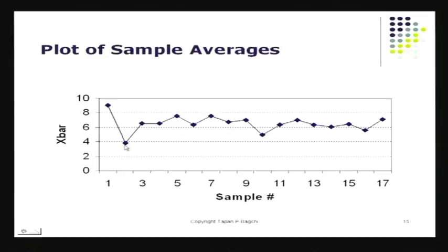So again, let's take a look at it. We saw the plot of the raw data. The same data was converted into X bar, and I'm going to be showing you how to do that. You have a collection of raw data, which are like individual measurements on these pens, dimensions of these pens, and you do a simple calculation. You calculate the quantity X bar from the X values. So you've got X1, X2, X3, X4, X5. These are 5 individual data points. You'll calculate X bar, and as the name implies, X bar is the average of those Xi values.